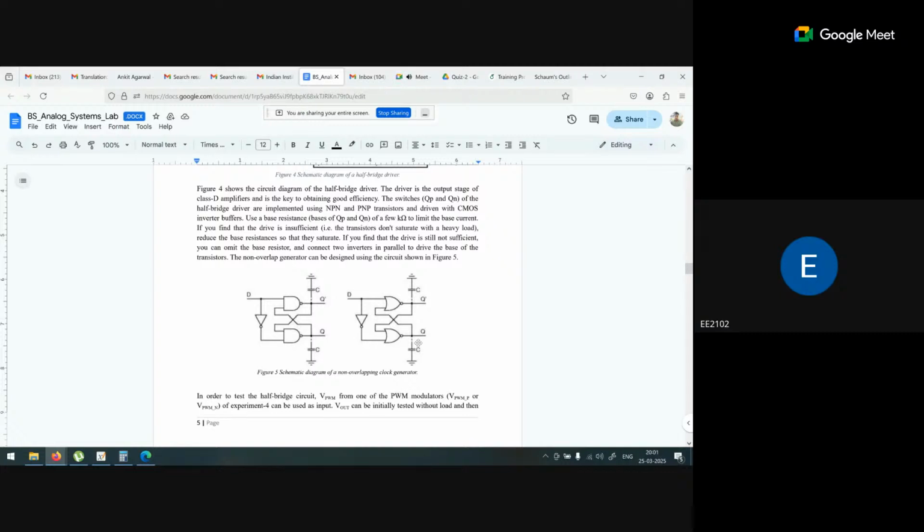Now, if we provide the PWM pulse, when the pulse is positive, that means the pulse value is 1, one gate will be working as high and the other gate as low. Second, if my pulse is negative, that means the lower level or zero level, the other gate that was previously low will now be high, and the first one is low.